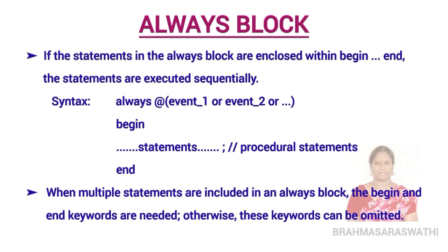The next point is if the statements in the always block are enclosed within a begin and end, the statements are executed sequentially. This means the always block has the begin and end block. Between the begin and end there are statements. These statements are executed sequentially. You observe the syntax on display: always @ (event 1 or event 2 and so on) begin, statements, end. These statements are called procedural statements.